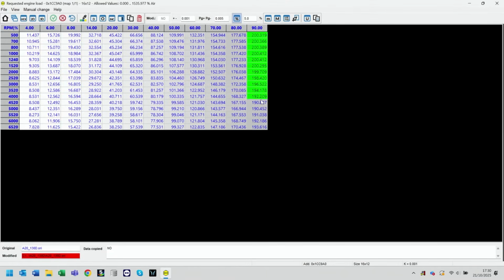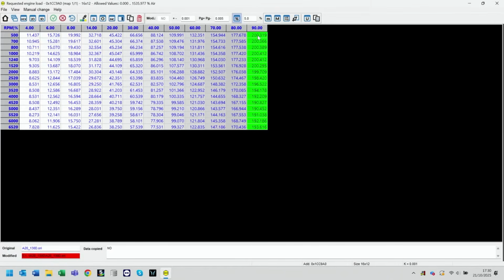We could just take the value of 200% of air on the table that we've already seen here, but because we're raising the boost up a little bit more, we might have a little bit more of a spike in our boost, our overboost, which is a normal operating function of the engine. It's not a sign of bad tuning, it's a natural characteristic of how these engines work and operate, all turbocharged engines. We need to make sure that our request sits comfortably above our limit. If we work our calculations out, we know 200% of air, take our 70 off, gives us a 130 on there, so 1.3 bar, so we're quite happy at that point.